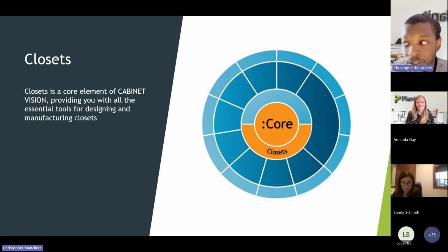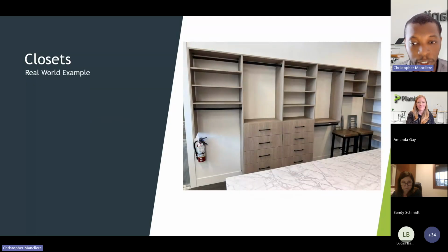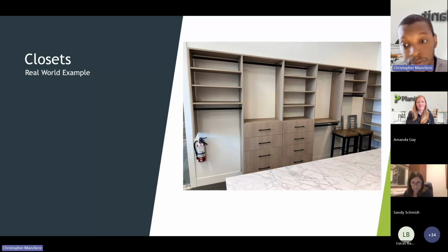So first thing in the closet package is what type of closet can you do with this add-on? That will be really like the typical closet that you will install in a residential or sometimes commercial project. It's made basically mostly of parts assembled on site using connectors. So you will have, for example, cam locks or Rayfix connectors that will get, for example, the panels connected with the tops, the fixed shelf, and the bottom.